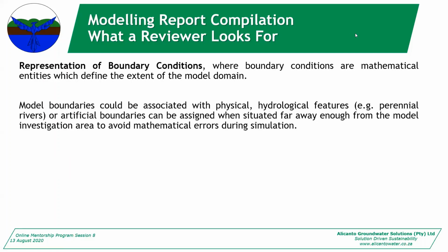Okay, so then in your report, you need to defend your boundary conditions. Are the boundary conditions reflected properly? Are they defended properly? Your boundary condition is a mathematical entity which defines the extent of your model domain. We'll go through this a bit better with the mining one, because then I can show you some mining models and boundaries that we actually use.